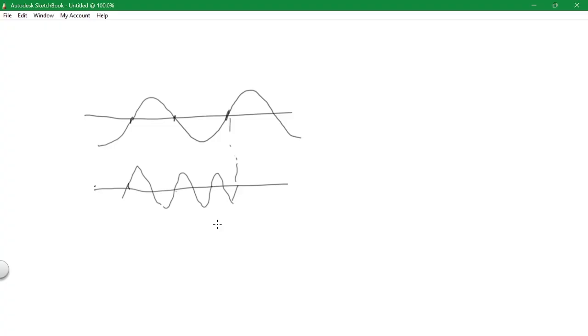Now, what does this do? Okay, as you go higher in frequency, what happens? Okay, 1 over j 2 pi f c and j 2 pi f l. Which one of these, as you go up in frequency, gets smaller? As you go up in frequency, the x sub c goes down.